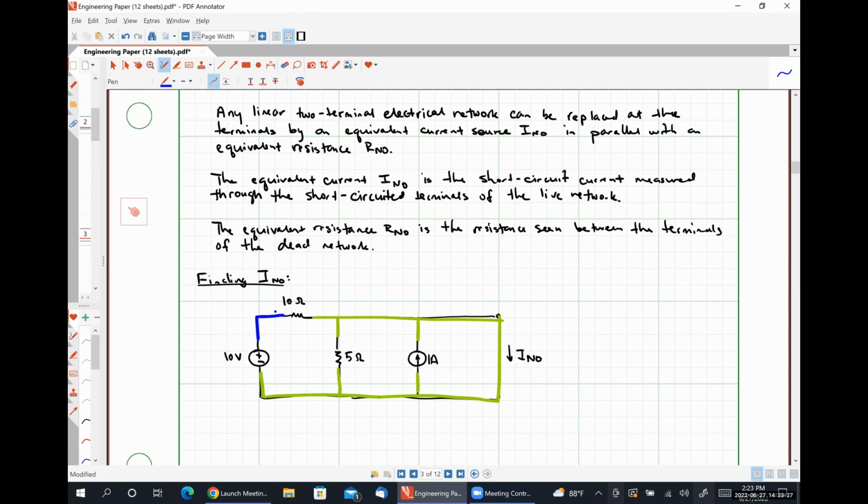So this is going to be a little bit awkward here, but we can definitely get through it by realizing a couple of things, okay? So the first thing that I want us to look at here, this isn't going to be a strict nodal analysis here because we really only have two nodes. If we chose ground to be the bottom node, then that would tell us that the blue node is at 10 volts, which we could get just by looking at the circuit anyway.